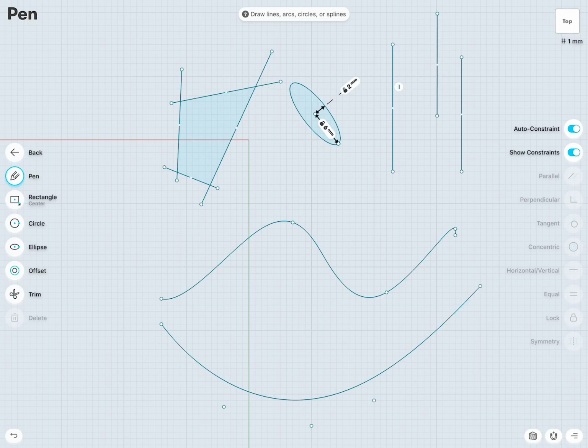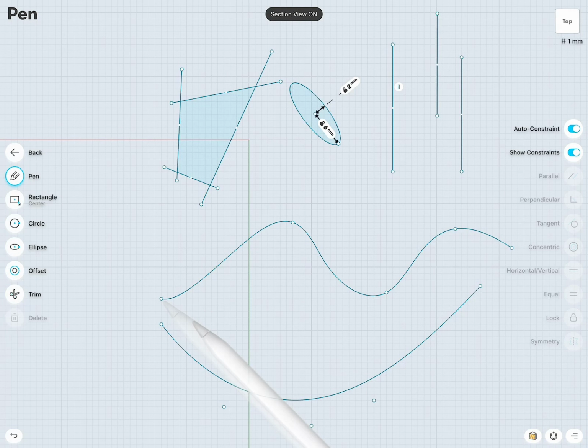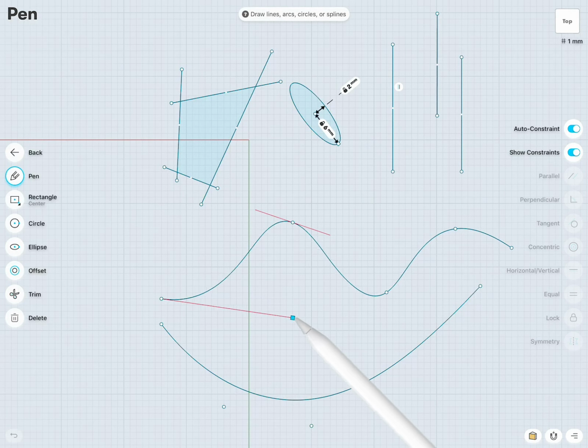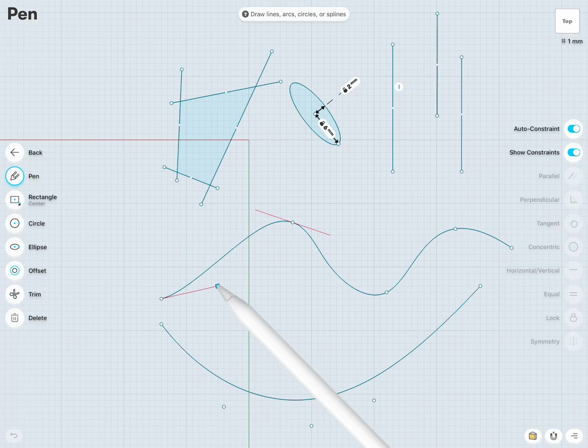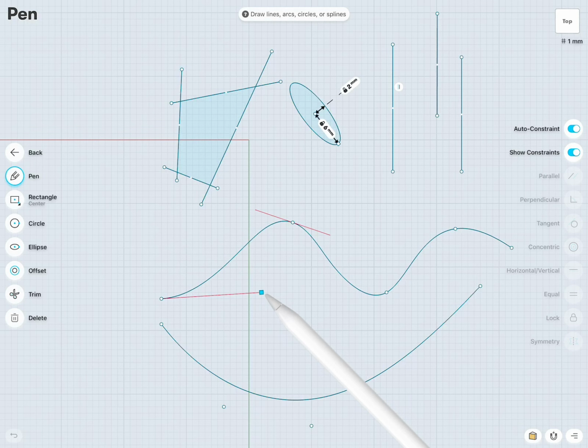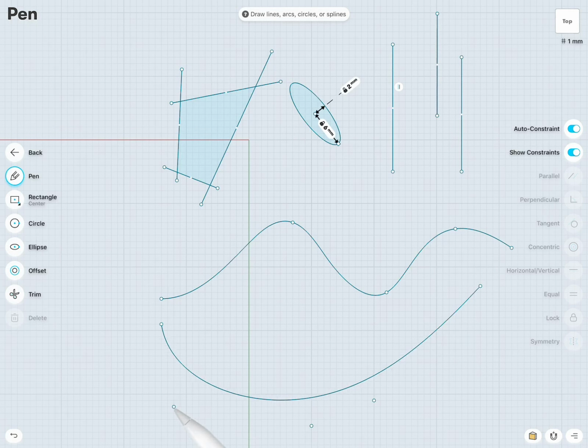Now you might ask yourself, where is the difference between these two curves, or when should I use which one? From my experience as an industrial designer, the fit point curve, so the first one, is very good when you want very even and smooth curves. Because as you noticed, when I select this point and move this handle, the whole curve updates. So think about this as a stiff material that we bend over these corner points, and it always wants to relax. The CV curve, however, is very good if we want to